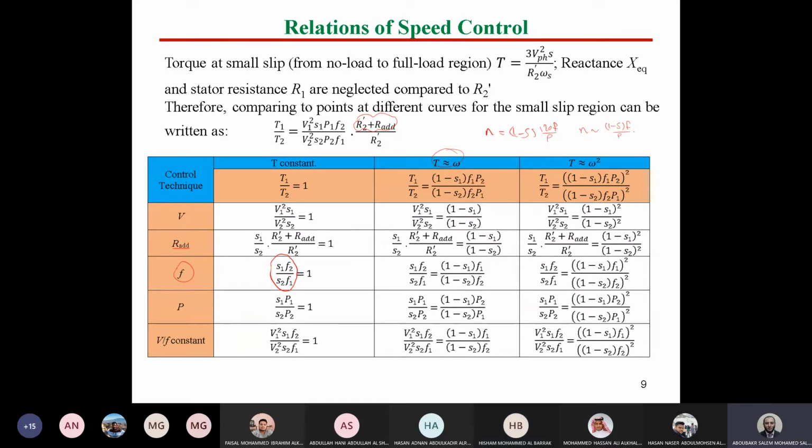Let's discuss the table again. We have now two relations, Shabab. We have the curve of the machine, which is this relation now, torque and parameters of the induction motor. And we have another relation, which is the load torque. We said together before, the operating point of any machine is nothing but the intersection between two curves, the machine curve and the load curve.